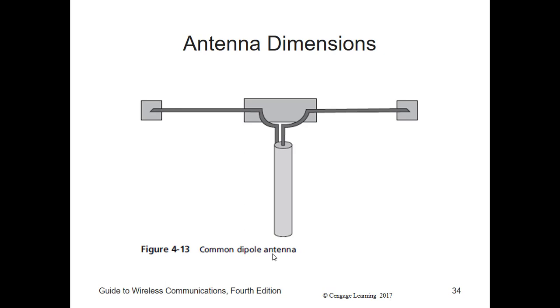The most common application for ground planes is on boats that have fiberglass hulls. Fiberglass is non-conducting and does not reflect radio waves. Therefore, antennas for nautical radios usually have either a horizontal metal plate near the base or alternatively four lengths of wire sticking out horizontally from the base to act as a grounding plane.